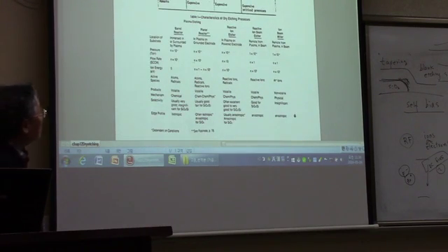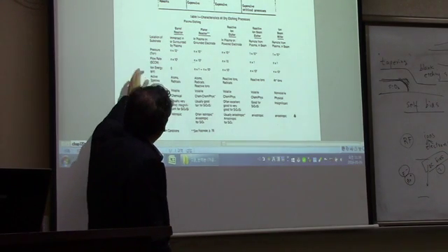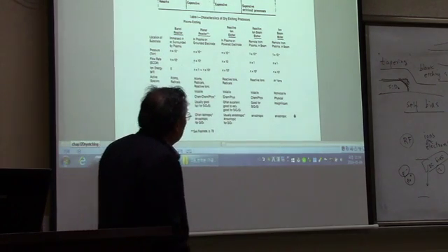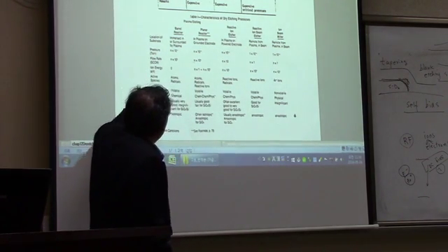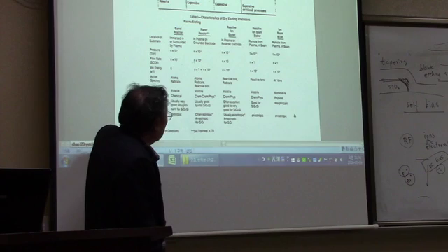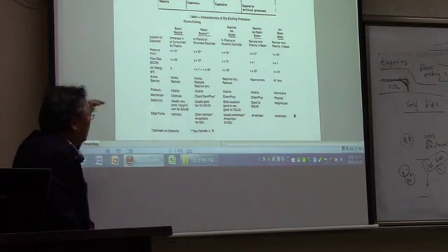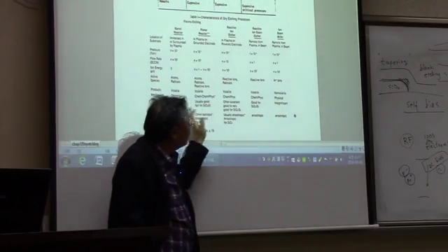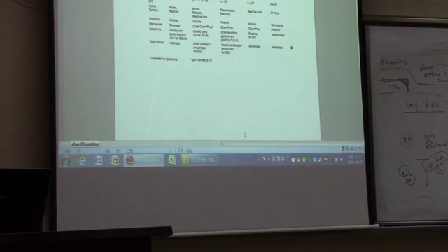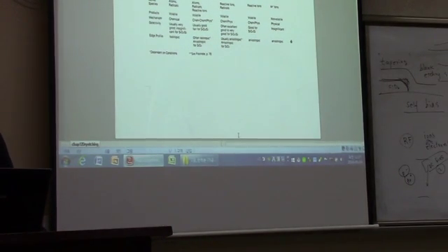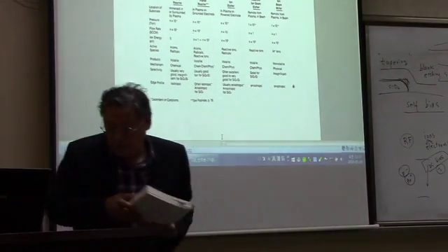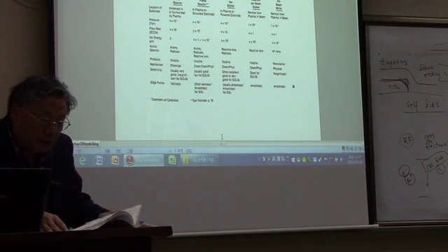And this is the final arrangement for the different dry etching techniques. You can see the important things here are the selectivity and the edge profile. That is related to the dimensional control. And as you move from here to here, everything becomes expensive because of the high energy and the low pressure. Okay, that is the end of the dry etching techniques.